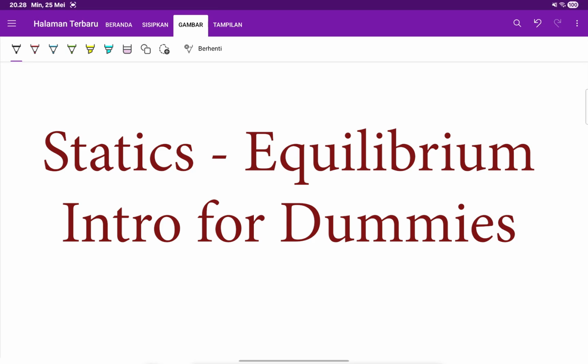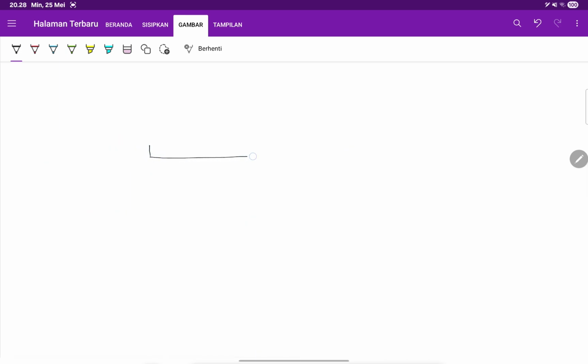So today we are going to solve the problem. So the problem is like this. Imagine you have a bar. It's not a bar, a beam. It's a pin joint, and one of them is a roller. So you have BY, and then you have AY, and then you have AX. Okay, and then there's a distributed load where the load is 100 newtons. And then there's another force, which is 50 newtons. The question is how to determine the equilibrium of this system, calculating the reaction forces AX, AY, and BY.